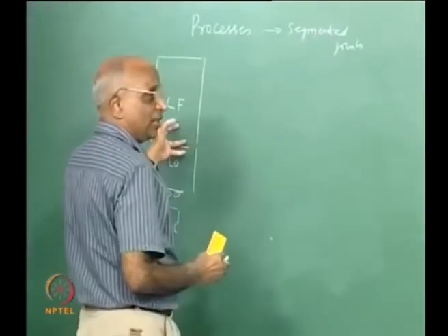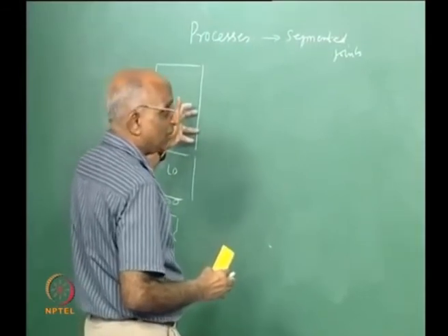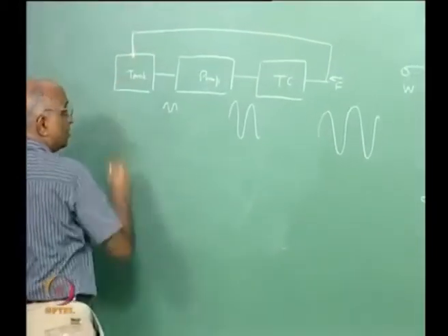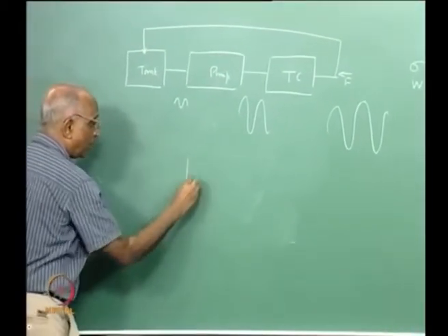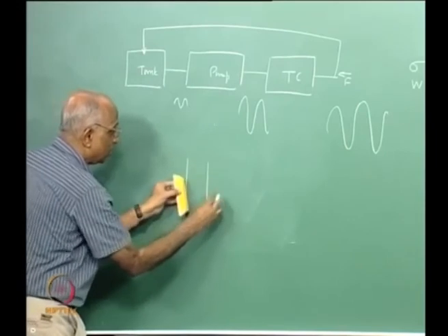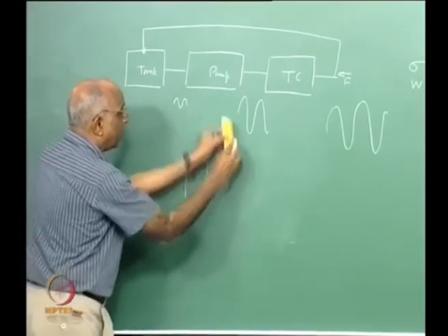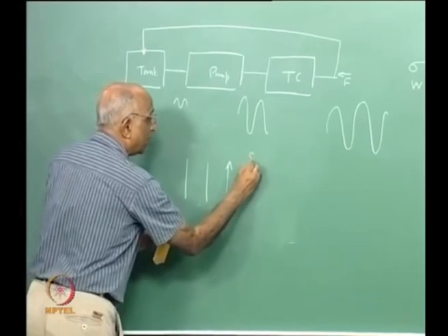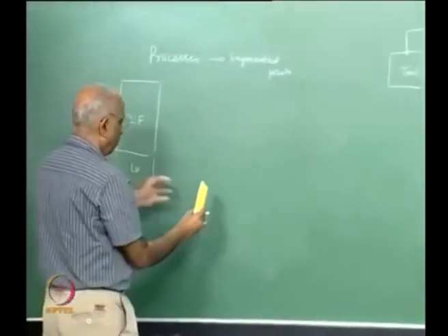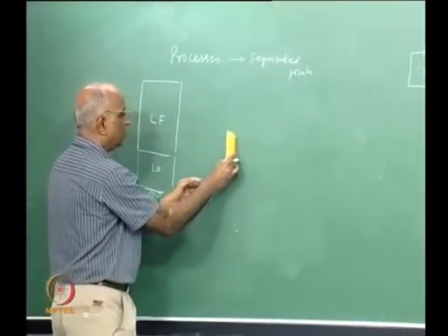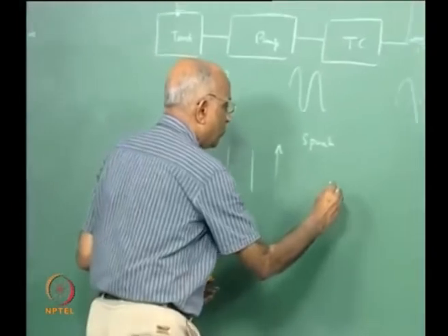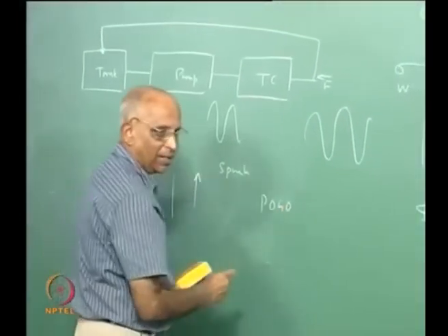The force further changes, getting in phase with the structural changes, and therefore I get feedback because of this force into my tank. It increases the structural oscillations, and my rocket now finds that some pressure is there, all of a sudden thrust increases, it jumps up and again comes back, again goes up, it goes something like in spurts. Instead of the rocket going normally, in a mission, under certain conditions it goes like this, like hopping. The name for this hopping is what we know as pogo. I will show this in a slide. Let us go back and see this.